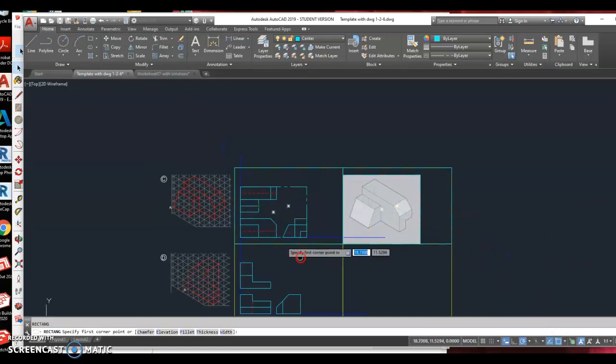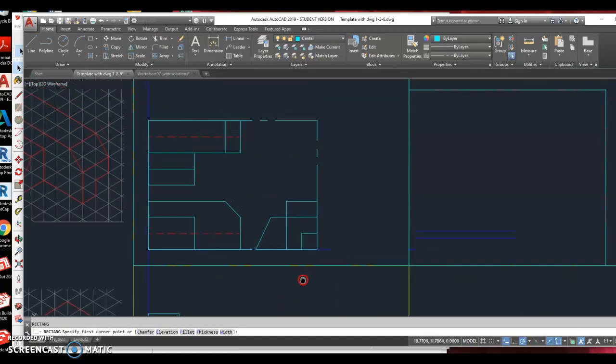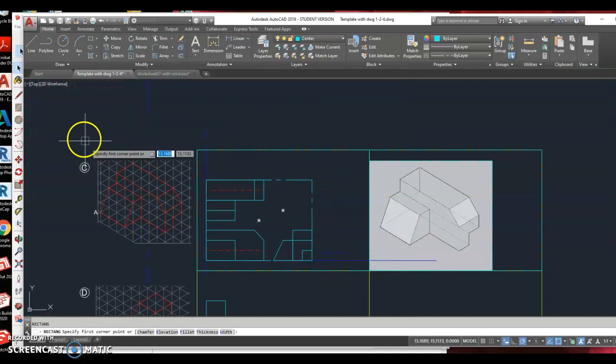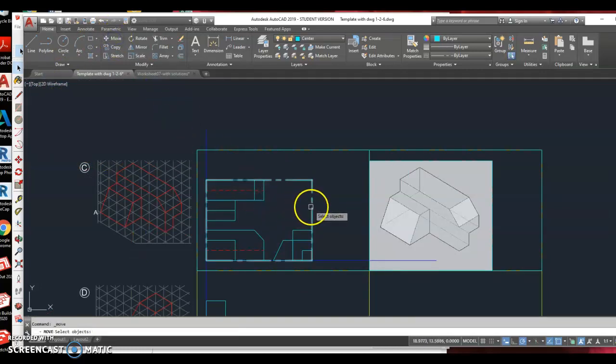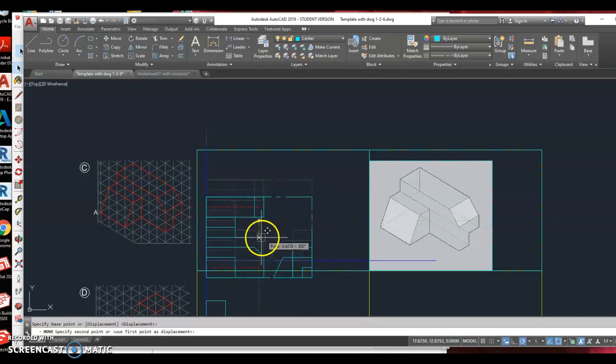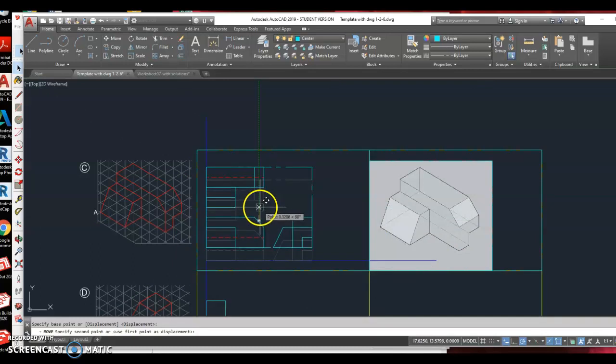And we're only going to be using that one snap, so I've taken everything else off. And now actually it goes pretty quick. You just have to be careful about what you're doing. I'm going to start the move command, and I'm going to move this object plus everything that's in it. So let me cross it. I don't want those, so I'm using my shift button to unselect those. And I'm done picking what's going to move, so I hit the space bar. Now I'm hovering by that rectangle I drew, and I see that the geometric center snap has highlighted with the green circle around the asterisk. So it's ready to select. And so I click, and now it's moving the objects I picked.